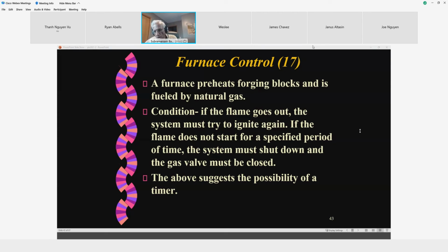Well, the one that comes on for a long time and then goes idle for a long time is an inefficient furnace. Okay, low efficiency furnace, as they call, or it could be mid efficiency. The one that comes on and off very rapidly is a high efficiency, but if it is a high efficiency furnace, the exhaust doesn't go through the roof. It is on the ground level, so you may not see it. Okay? What is the logic behind all this?